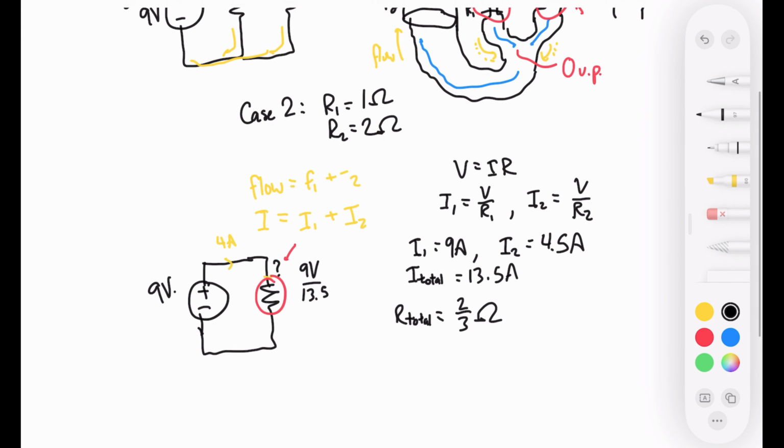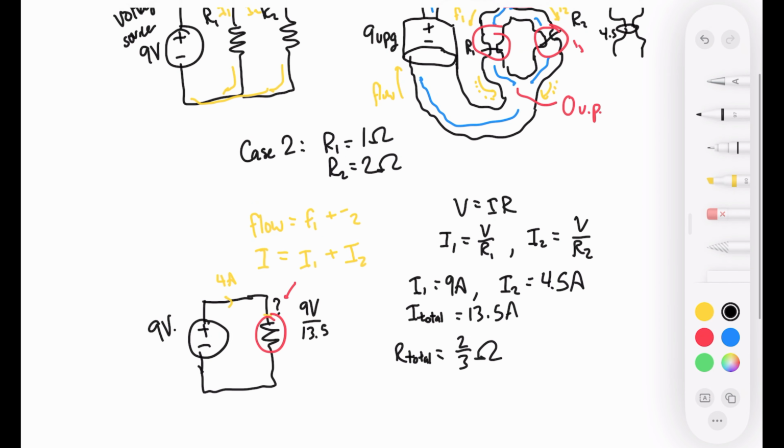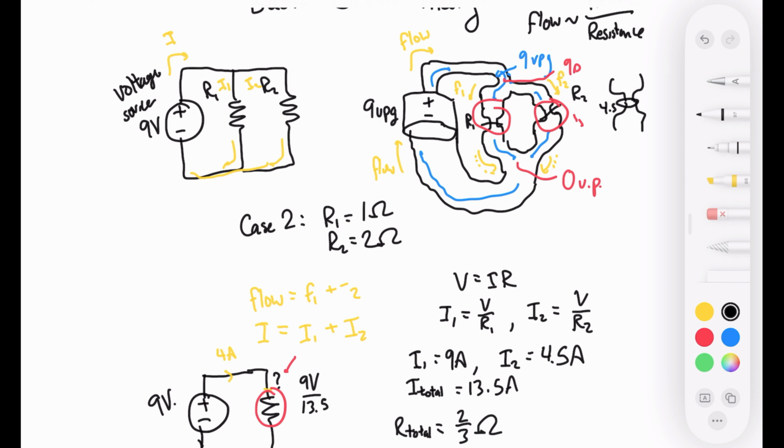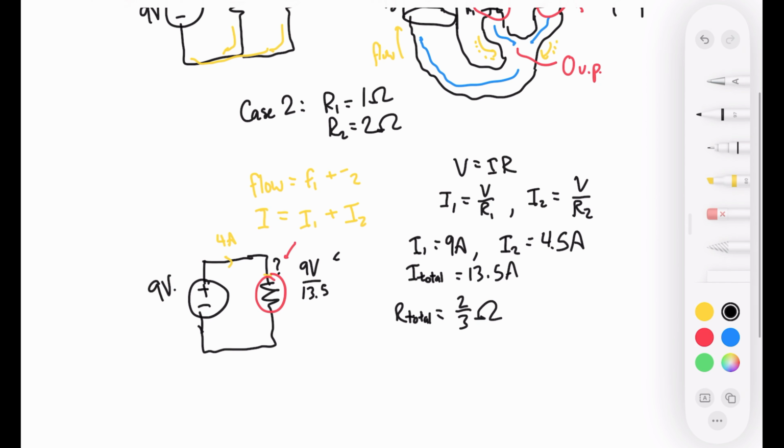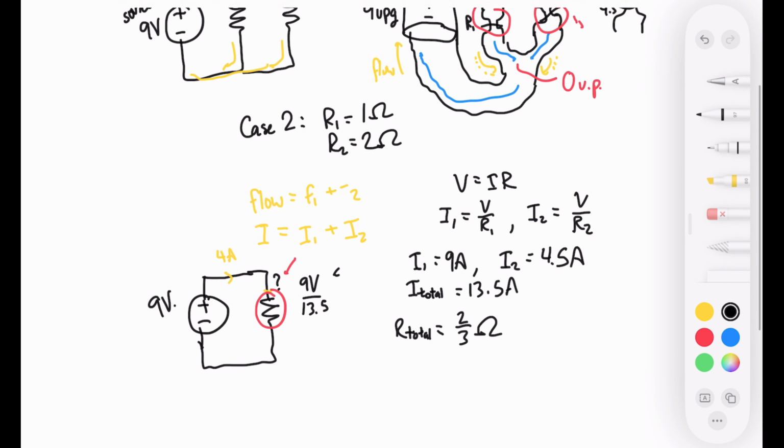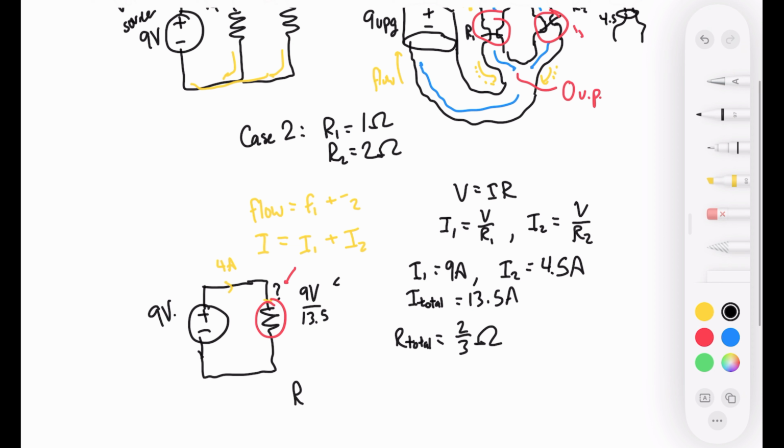Now, in general, whenever you have however many of these in parallel, because you know that the currents add together and the voltages are the same, you can basically solve these because you know the voltage dissipated across each of these is the same as the voltage dissipated across here, and the currents add. So basically if you solve this around, you get that R total equals 1 over R1 plus 1 over R2 plus et cetera, et cetera. So rather than adding, you're kind of adding the reciprocals and then taking the reciprocal of this.